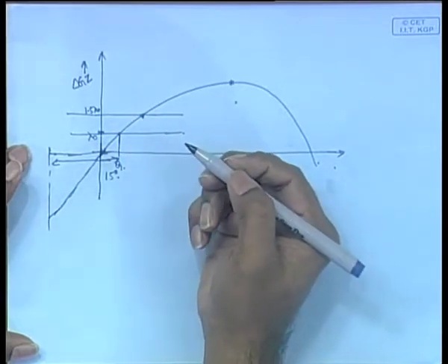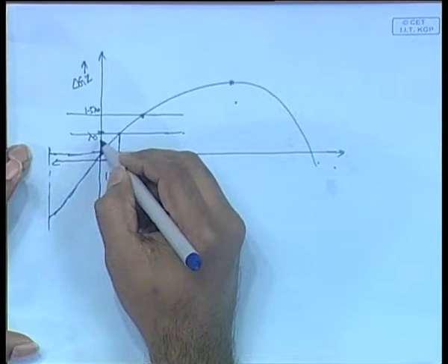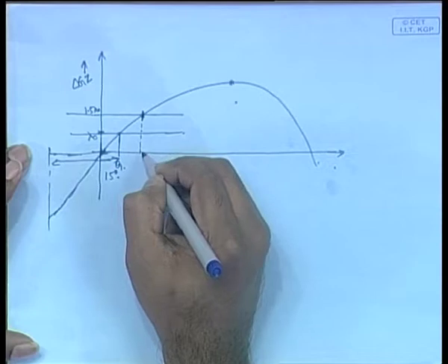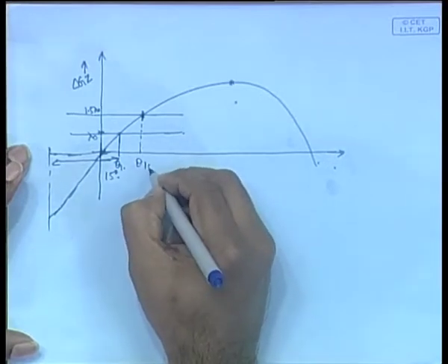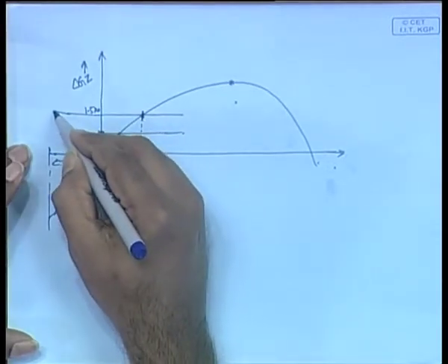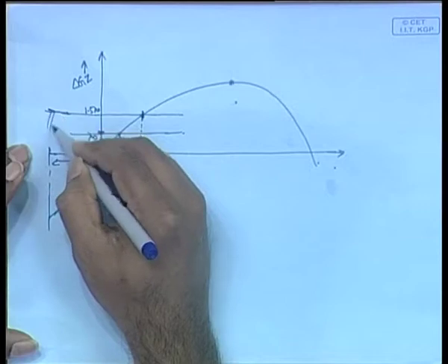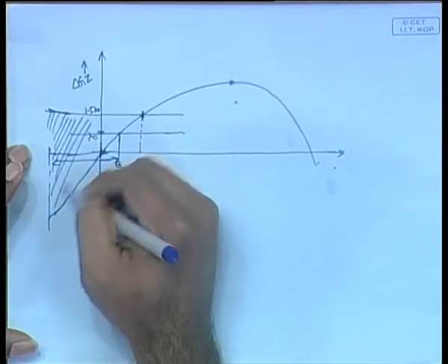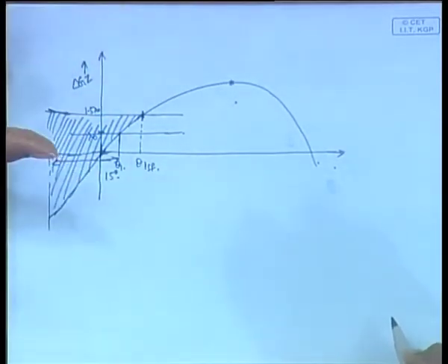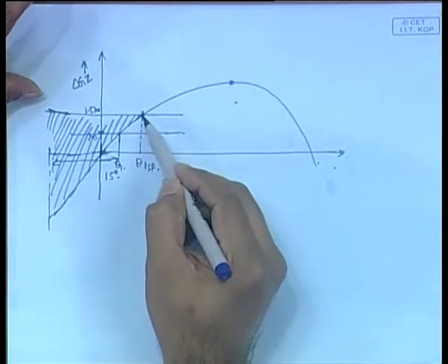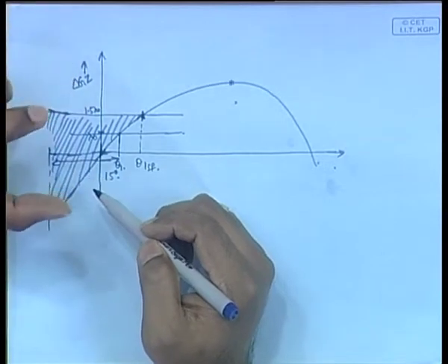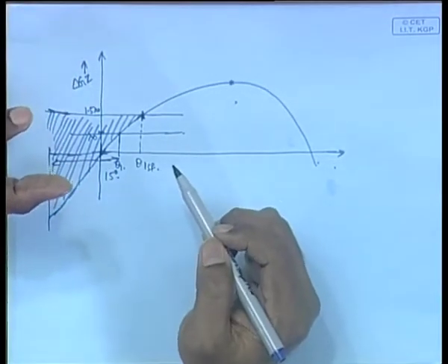Then, once you have that, this is the angle where it hits GZ, this is like your theta 1 with a safety factor, theta 1 with a safety factor, that is here. Now, you find the area under the GZ righting arm curve, under the righting arm and heeling arm curve. Okay, the angle between this heeling arm 1.5 lambda 0 and this righting arm. So, the area under that curve will give you the net amount of energy that is input into the ship because of the wind.